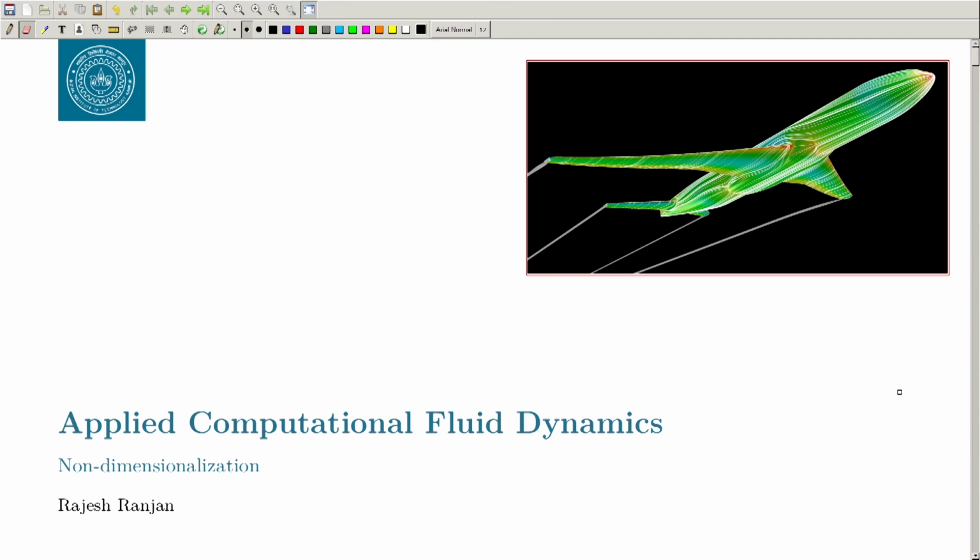You can use a scaled down model. The same aircraft, the same wings, same empennage, same control surfaces, same flaps, slats and everything that you have in the A320 will be there in your scaled down model. But you will get some result from the wind tunnel, so how do you make a relation with what is happening in your real flight situation? There must be some number that is governing the dynamics, so that you can say that what is happening in this model must also be happening in your real prototype. We will look into that.